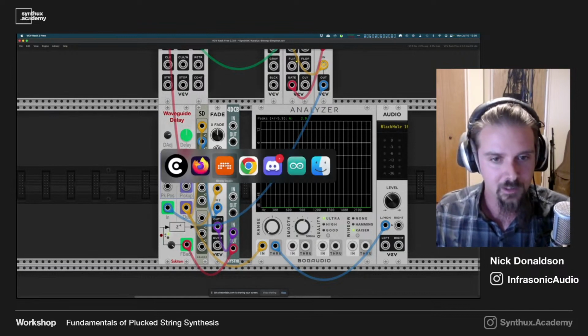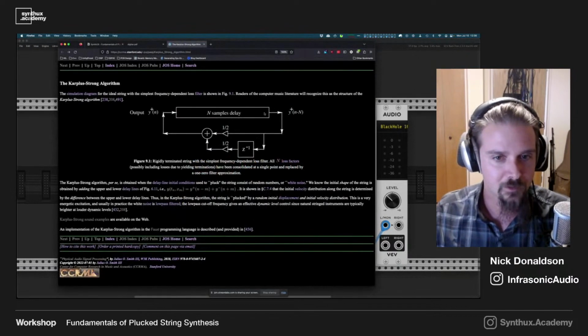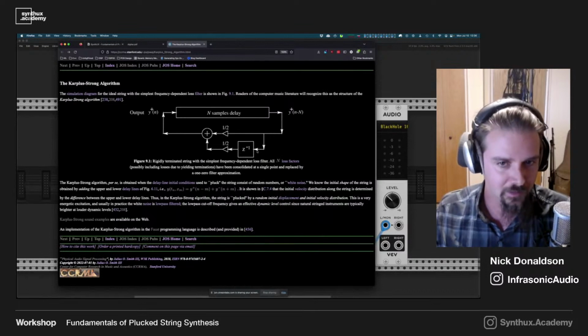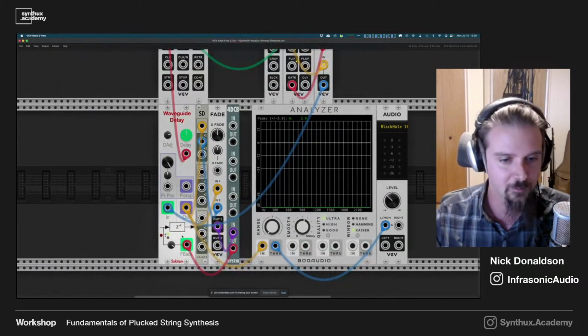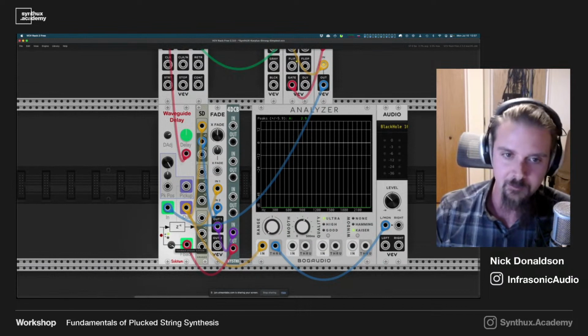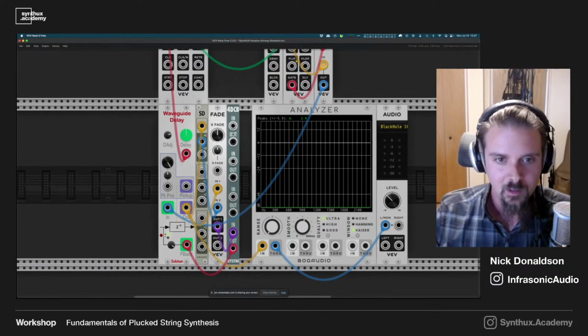And what that's doing, much like we see in this diagram, this would be the direct output into one input of the crossfader. This Z^-1 is a one sample delay. And we're summing those together, and we're multiplying by 1/2 in this diagram. We're not doing that here. We're compensating for that by lowering the feedback amount, but the effect is the same.